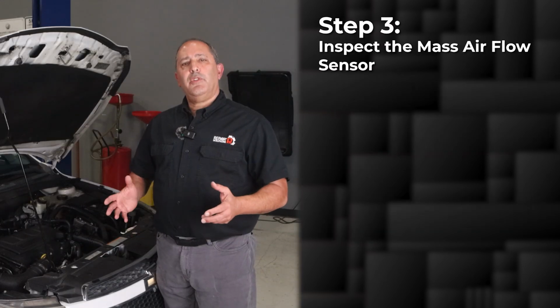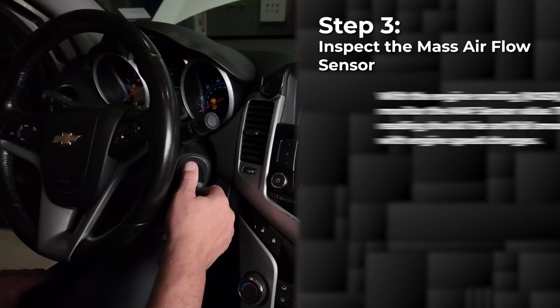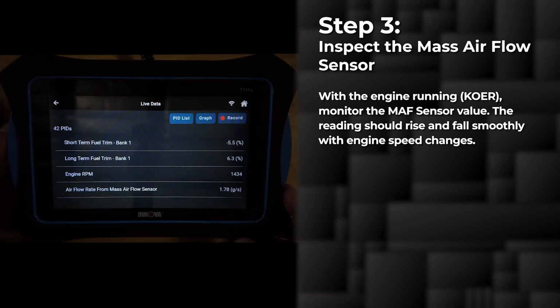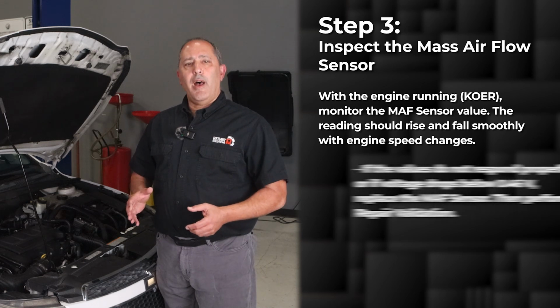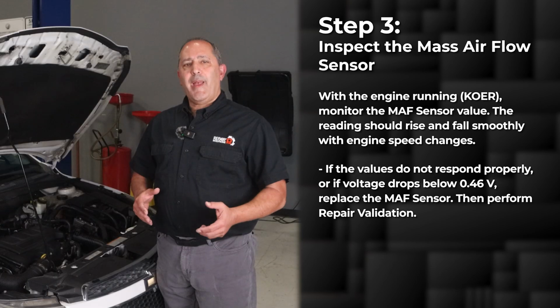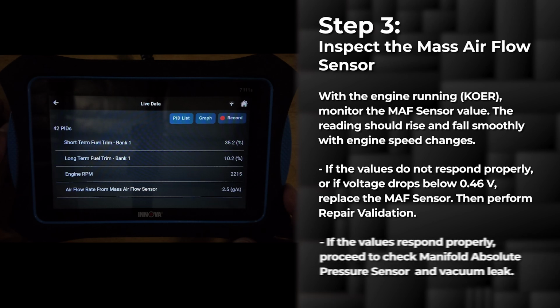Step 3 is to inspect the mass airflow sensor. Using scan data, start the engine and monitor the mass airflow sensor values. The reading should increase smoothly as the engine RPMs increase. If the values do not respond properly, or if the voltage value drops below 0.46 volts, replace the mass airflow sensor and perform a repair validation. If the values respond properly, proceed to step 4.